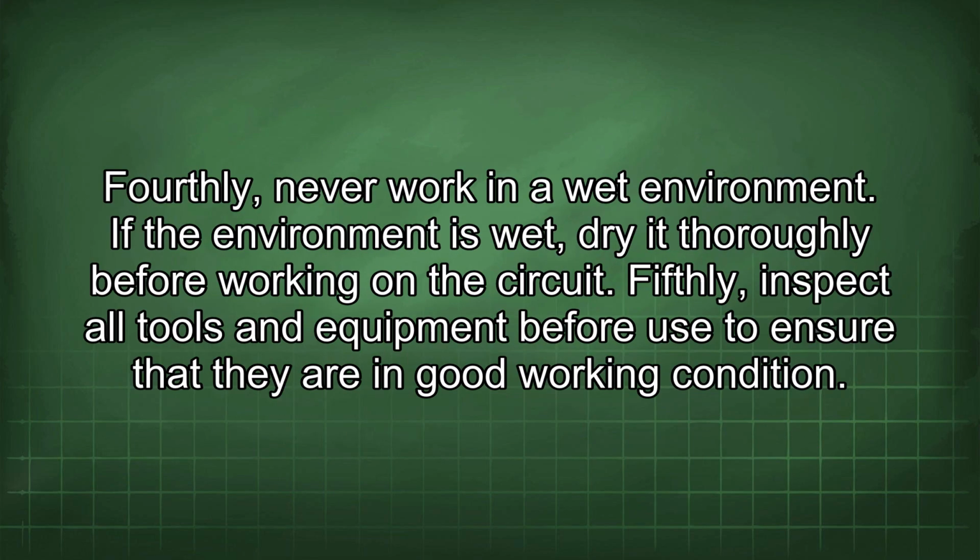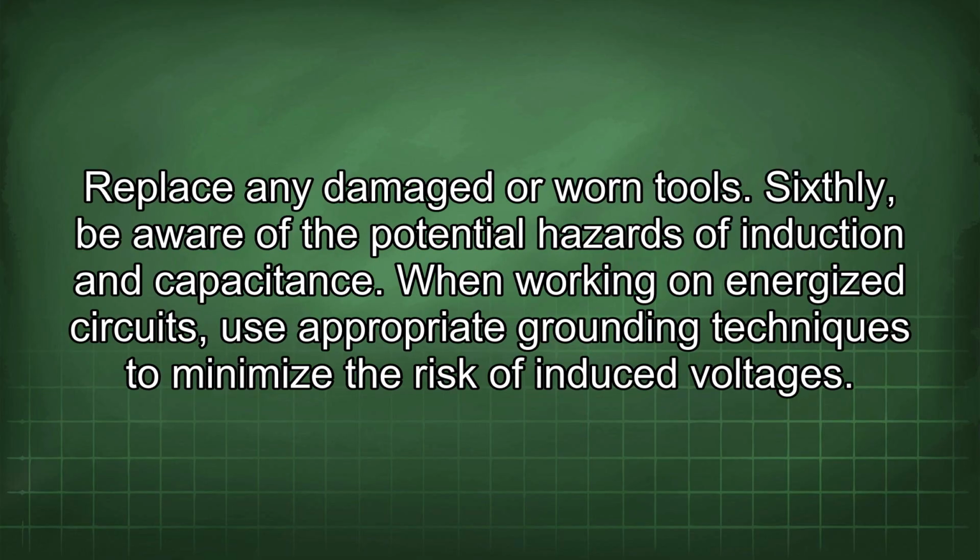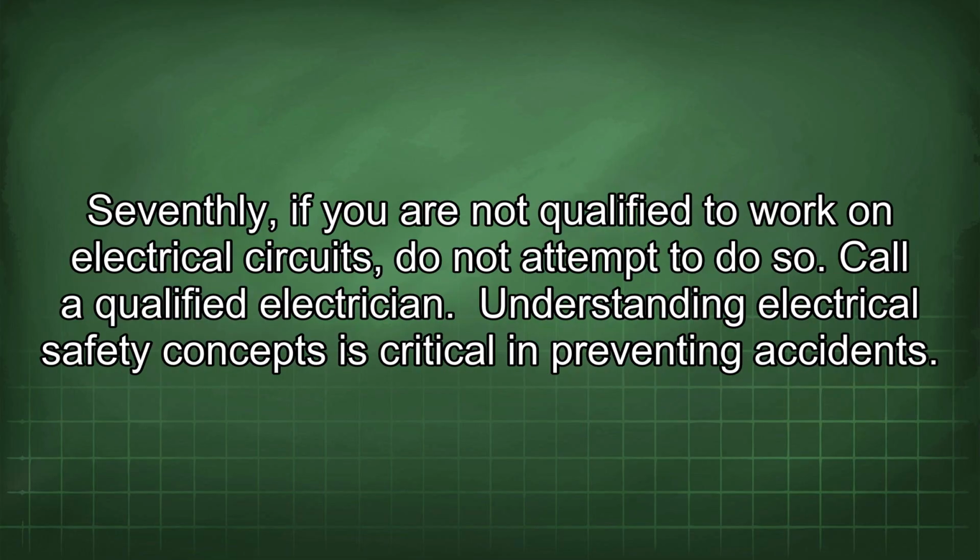Fourthly, never work in a wet environment. If the environment is wet, dry it thoroughly before working on the circuit. Fifthly, inspect all tools and equipment before use to ensure that they are in good working condition. Replace any damaged or worn tools. Sixthly, be aware of the potential hazards of induction and capacitance. When working on energized circuits, use appropriate grounding techniques to minimize the risk of induced voltages. Seventhly, if you are not qualified to work on electrical circuits, do not attempt to do so. Call a qualified electrician. Understanding electrical safety concepts is critical in preventing accidents.